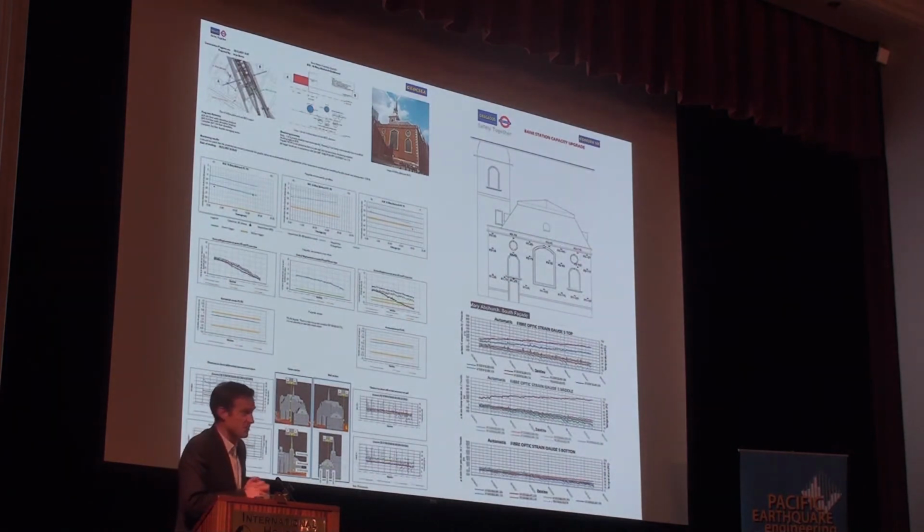Our fiber optic installation was integrated directly into the contractor's real-time measurement system. The nice thing about this is, you're not expected to see any of this, but all of the left is their instrumentation system. All of the right is our fiber optic one, where they're getting real-time strain measurements at basically 80 locations distributed around the building, and they have the trigger levels to make decisions or to implement mitigation measures if those strains were getting too large.